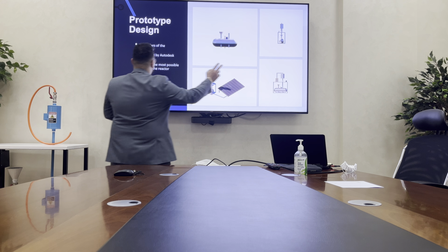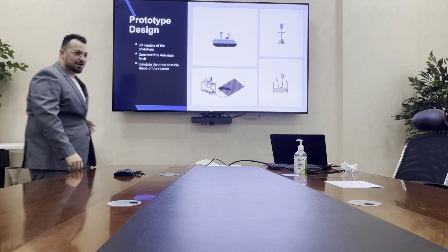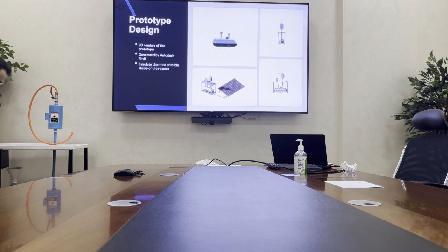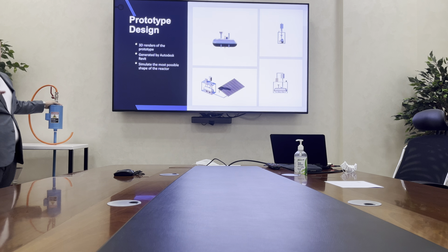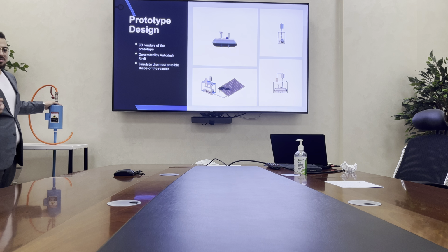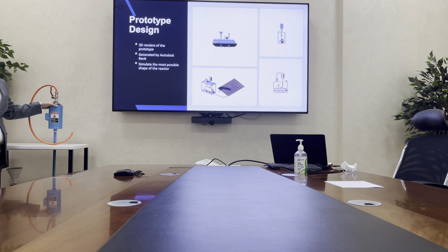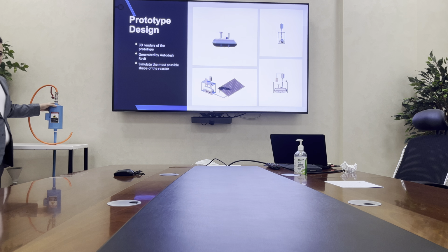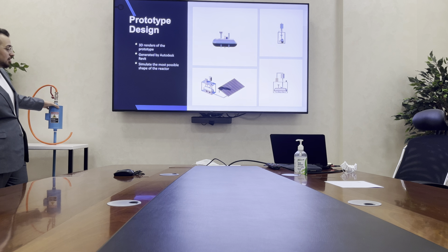And then we converted this beautiful drawing to real life, as you can see here. There's the reaction vessel, pressure gauge, safety valve for safety reasons, temperature gauge, and this is a multi-filtration system. The multi-filtration system is to filter out the water vapor and the carbon monoxide. As we know, the PEM fuel cell is poisoned by carbon monoxide, so we used activated carbon and silica gel.